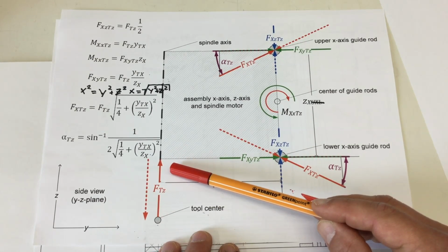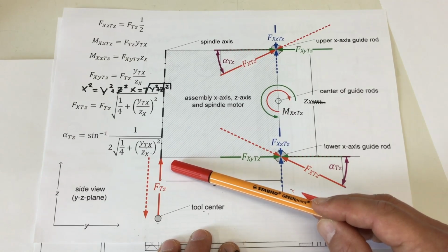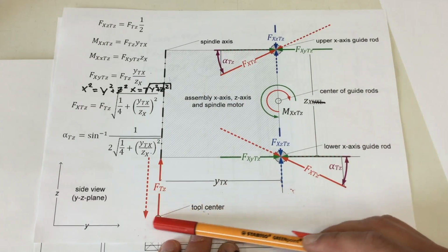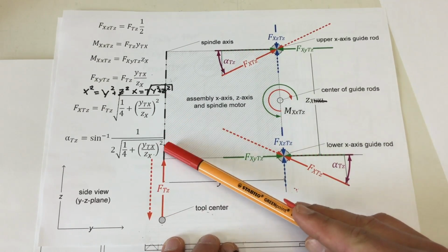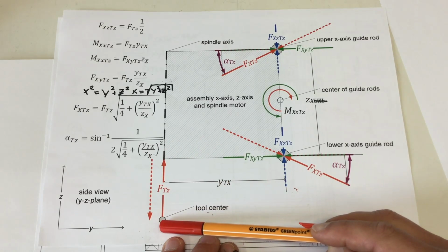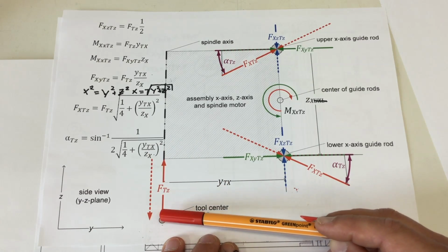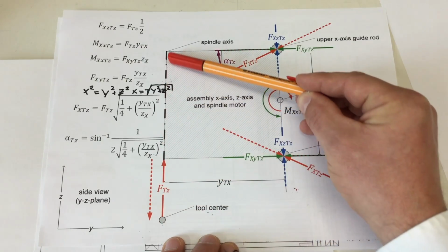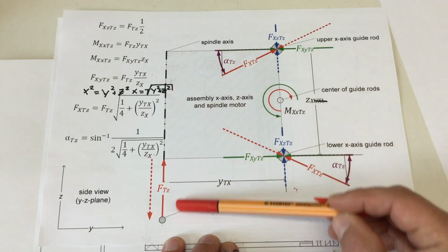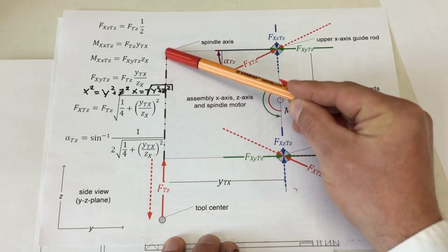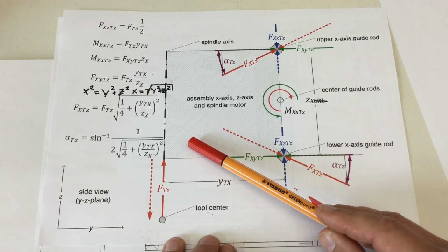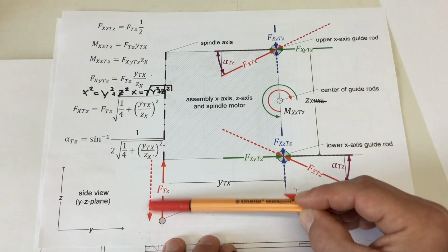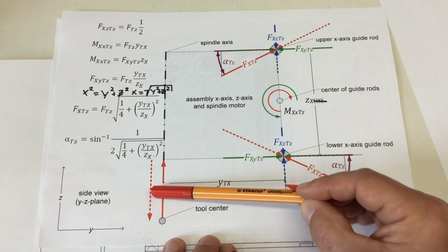One example comes to mind where it might happen. For example, you're drilling down into the material, your spindle stalls, your tool got stuck, and you're not around to press stop on the machine, and the machine tries to retract the tool, moving the z-axis upwards, and your tool is stuck, and well, my z-axis will be able to exert 188 newtons. So yeah, there are cases where this can happen.